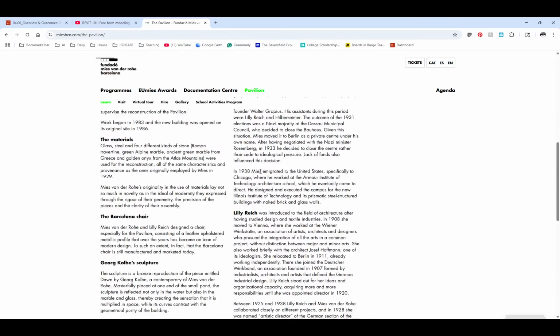And so our walls in our Revit model don't really look like that. Our walls look solid. So how would you build that? If you use the Architecture tab and Wall, there isn't anything really out of the box, right? These things are solid. Bricks, maybe, if you change the size of the brick, but generic, that doesn't give you the lines that you want. I'm going to argue to you that we should be using a curtain wall, specifically a no grid curtain wall, and I'm going to explain that here in a second.